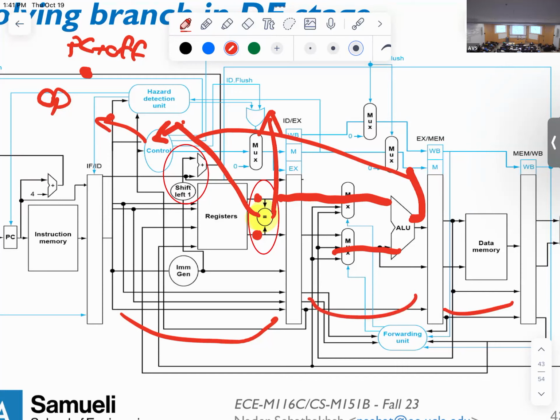There are trade-offs, but if you design this very fast, and this part is happening with the register read, it's not really a big problem. The slowest part is this part, because you need to read the register file and then do the comparison. But the comparison is very simple logic, so it's not significantly adding to your design. This data memory is really the slowest among these.